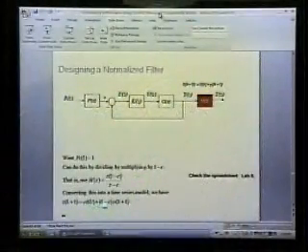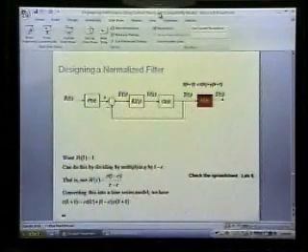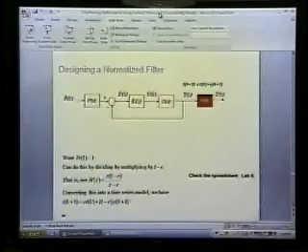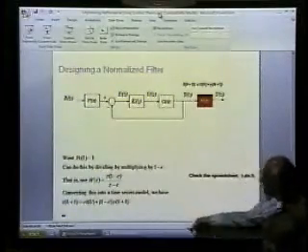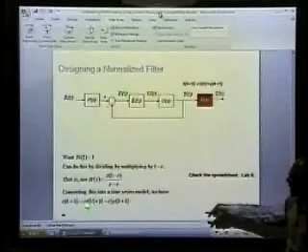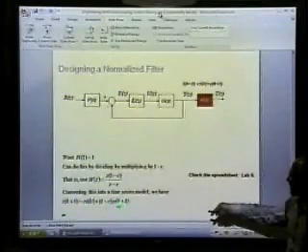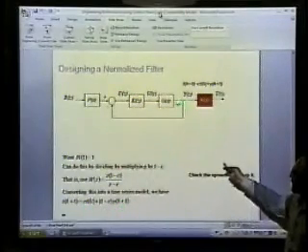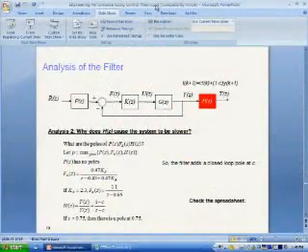That means we have a 1 minus c for the y(k+1). So we've got c plus 1 minus c for the y(k+1). It also has easier semantics, because it's basically saying c is a number between 0 and 1, and you're figuring out how much you're taking from the last value of the output versus the current value of this output. So it actually is a little bit easier semantics, and then you end up with the right end result. Okay, so at this point, that introduces our filter.